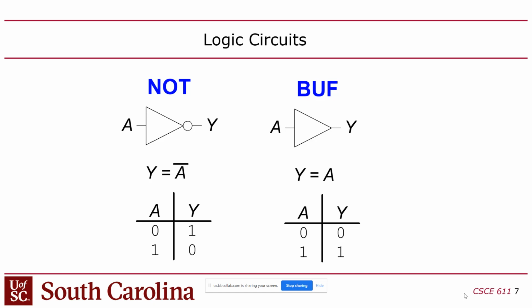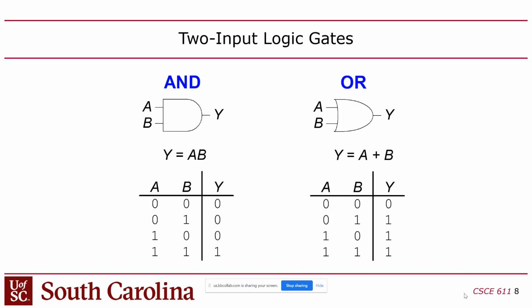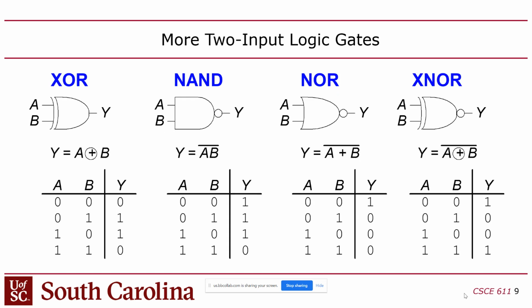Now there is something called processes, which follow sequential semantics internally, but when they are synthesized into gates, that process by itself becomes concurrent with everything else in your design. So you'll hear me mention a lot that the order of lines of the program makes no difference in Verilog.